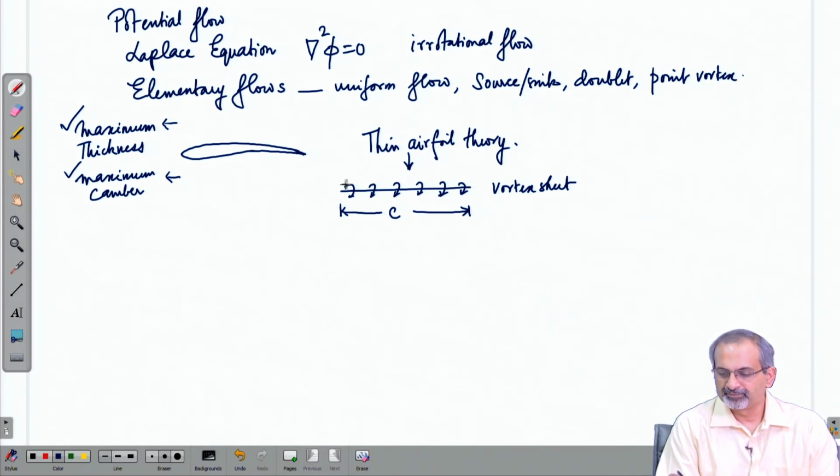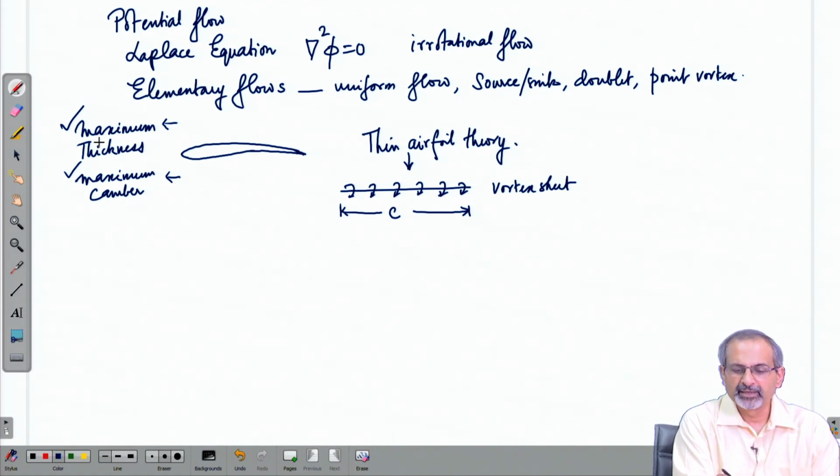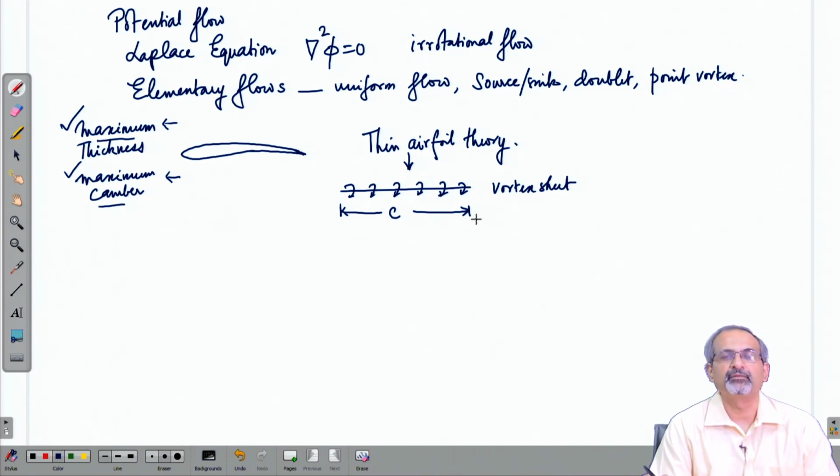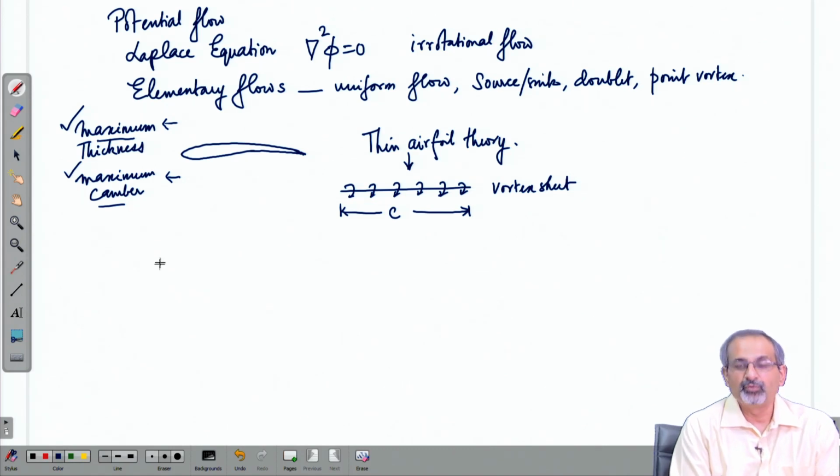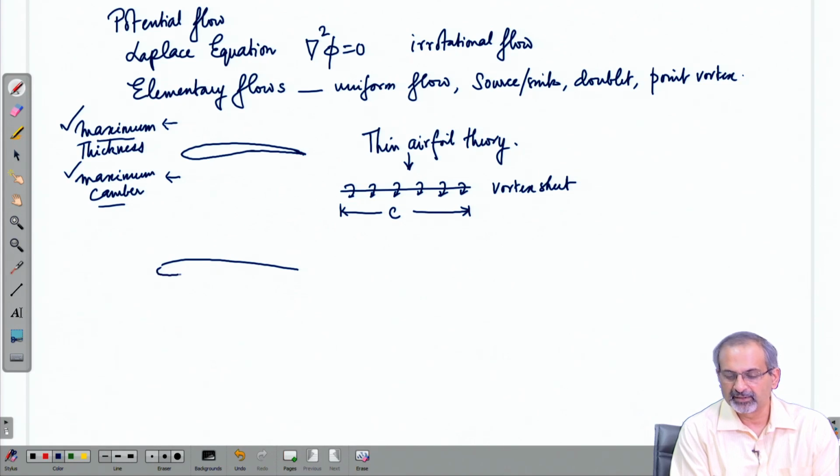There we had an analytical solution which could give us the solution to the flow. But the moment you make the thickness and camber vary quite a bit, there is no closed form solution available anymore. So, we then go for a numerical solution. We were discussing earlier what are the situations where CFD becomes important. So, this is one where you do not have an analytical solution anymore.